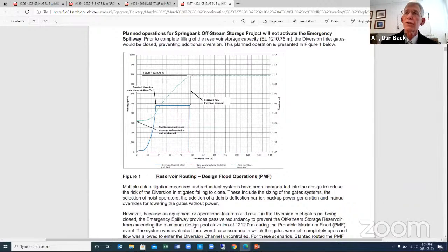There's a third analysis that's done, and that is a post-earthquake analysis, after the motion stops, when everything is static again. We make the assumption that the motion has caused some reduction in the shear strength of the soils in the embankment and in the foundation, and a post-earthquake analysis is done there. That was also done at SR1, and those meet the criteria as well.